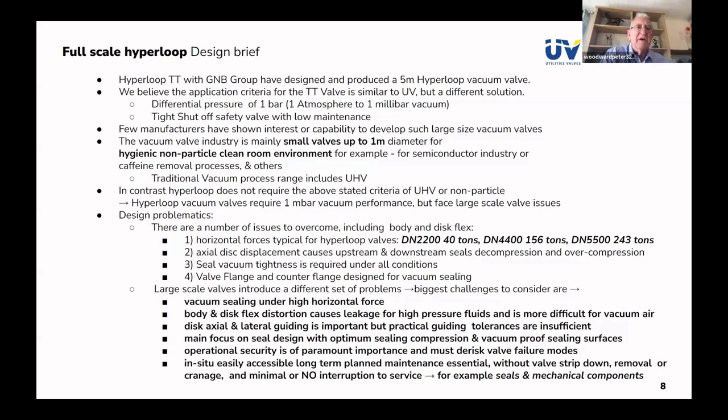So everything we've done is very much in mind of maintaining the valve in situ, even with man entry into the valve under safe conditions, to carry out, for example, seal replacement, which can be done inside in about 4 hours shutdown to completely replace the seals.